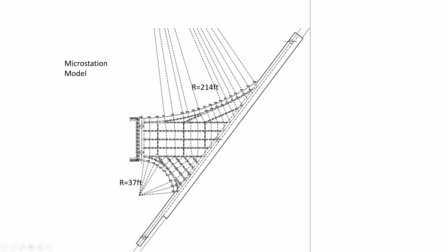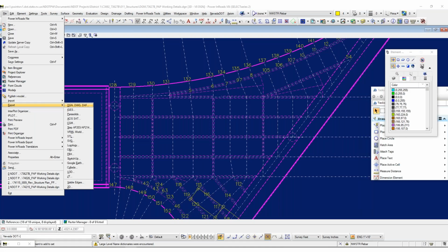There are intermediate diaphragms, which are shown here with the mouse, but not too many, like the 1, 2, and 3 only. The rest of these lines represent the slab, top and bottom. Here is how, after laying out all the elements in Microstation, I was able to export those in a DXF extension, so it can later be imported by MIDAS.